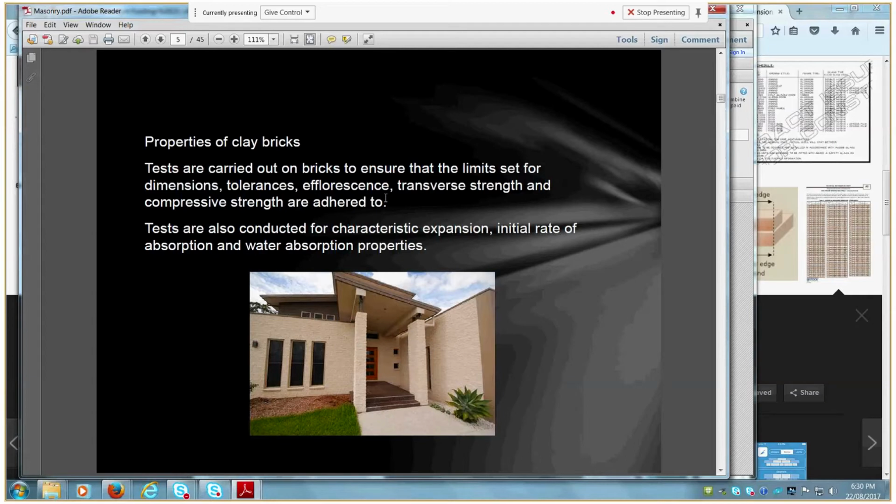The salt actually starts breaking apart your walls. Efflorescence is just simply the initial depositing of those dissolved salts. So you can get efflorescence where you don't actually have any moisture issues.